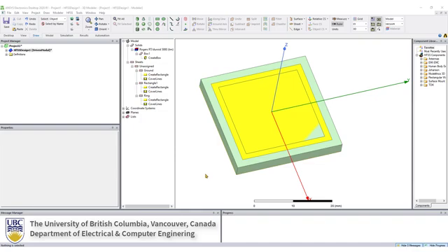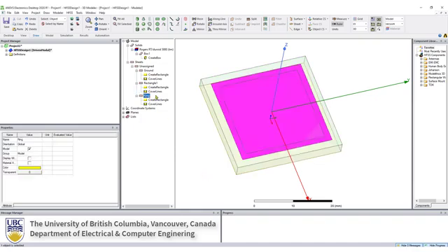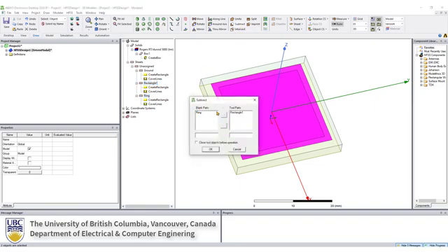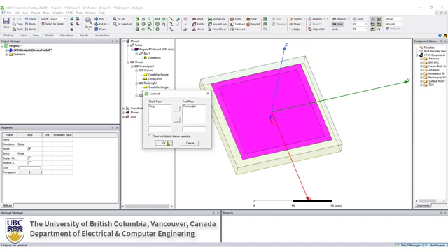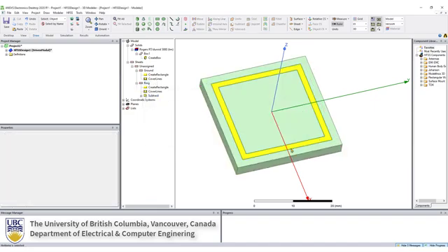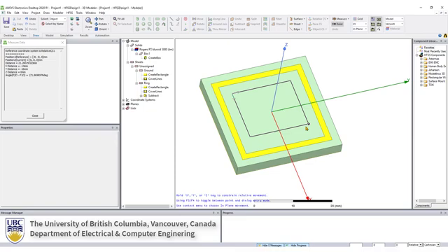Okay, now let's select this ring and then rectangle 1 and then go to subtract and make sure your blank parts is ring and the tool parts is the rectangle 1, and that would create this rectangle or the ring. Now the time for the inner patch,